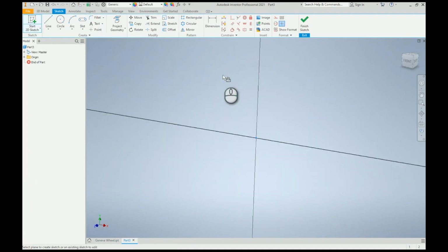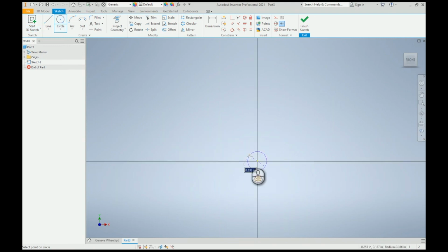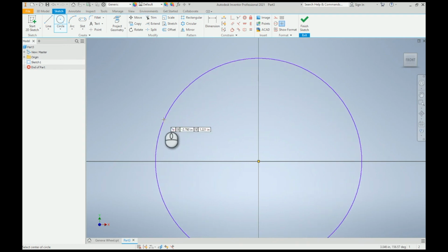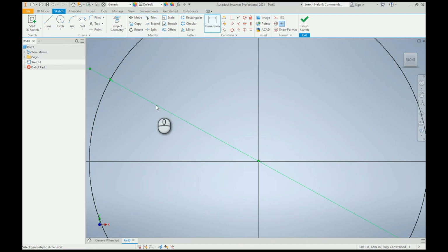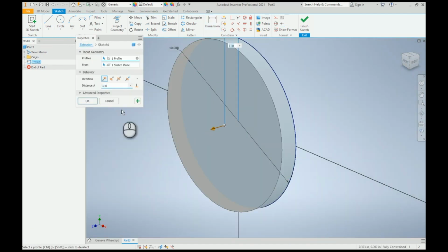There are many ways to design the crank wheel. I'm just going to model a common one in the shape of a disc. The diameter of it has to be larger than the rotation circle of the pin to be able to place it on it. The pin rotates in a circle of 8 inches, plus the pin diameter, it equals 8.75, so we are going to make a disc of 10 inches. Let's extrude it arbitrarily 1 inch in thickness.